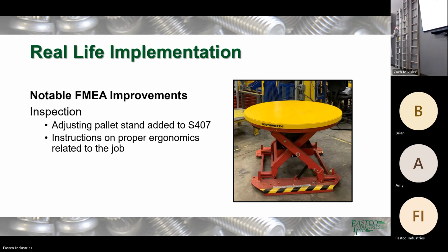And then, in our sort department, we have some skid stands, probably about that low, that they put their boxes on to take them out the box conveyor. What we decided to do was go with an air bag one, to where it'll be at a certain height, and as you put the boxes on the skid, it'll lower down. Not only that, it also spins, so they're not reaching around. When the box gets full on the skid and they have to go on to the next level, they can just spin it, so they're not reaching over it with the box.